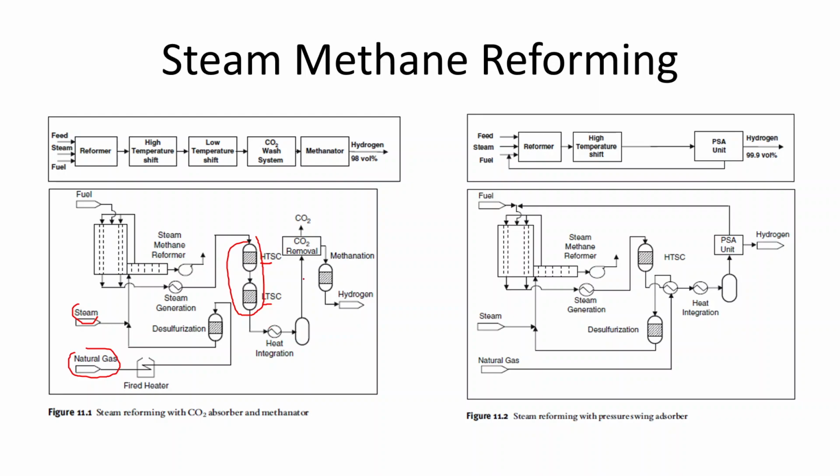and then they remove the gases, and then remove the heavies if any, and then there's the CO2 removal. And then if you have some CO, there is some methanation that happens to make methane. So we need to remove CO to make pure hydrogen. Having this methanation also consumes hydrogen, because CO plus hydrogen, we make methane, and in that sense, we are losing some hydrogen.